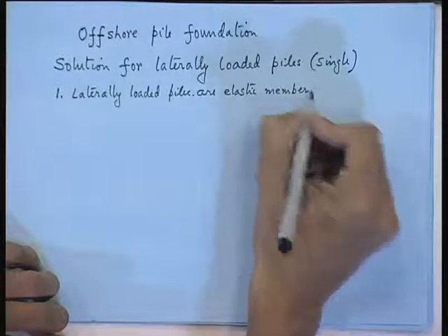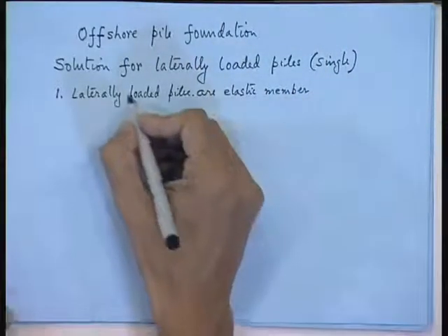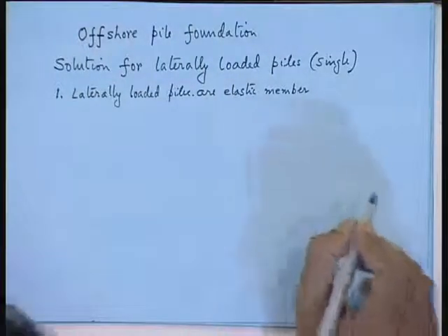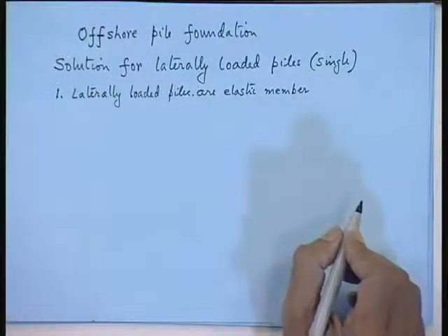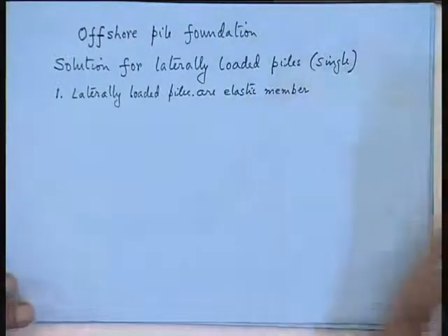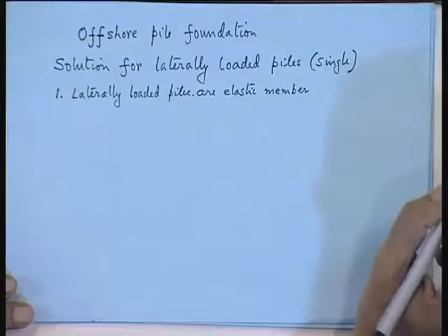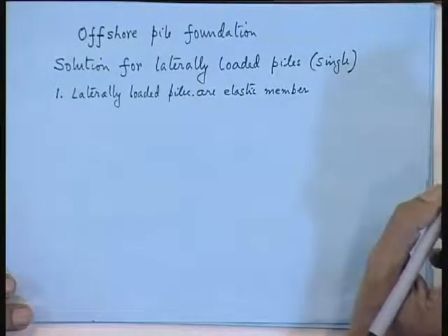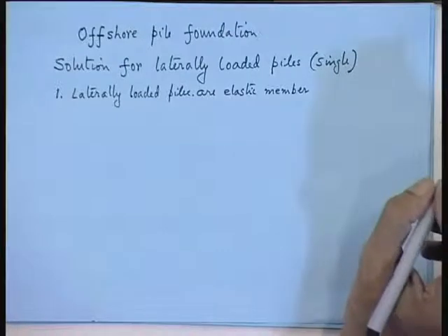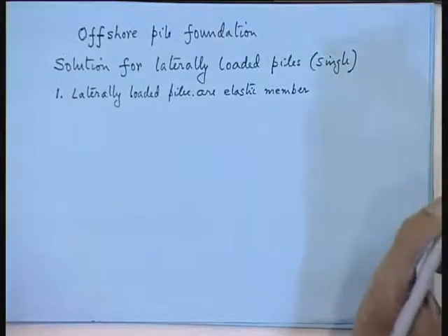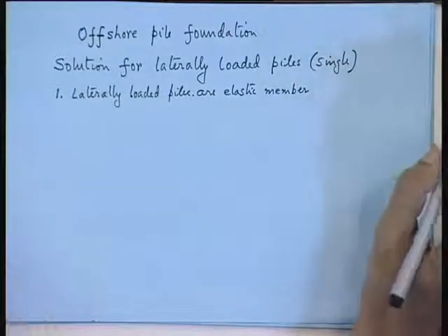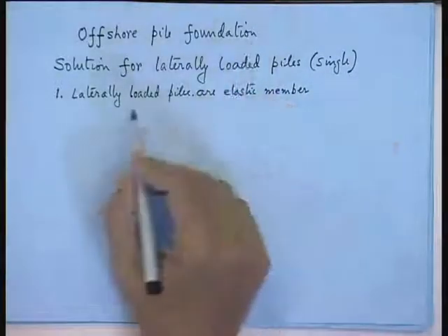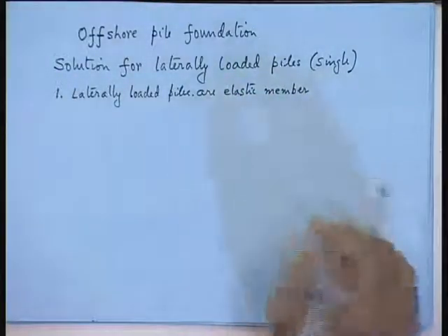We are not making analysis in the plastic zone. Normally, for failure of offshore structures, you make what is called an elastoplastic analysis. I do not know whether you have come across this term when you go in the failure mode actually. Anyway, we forget about that. So, we assume this to be elastic.